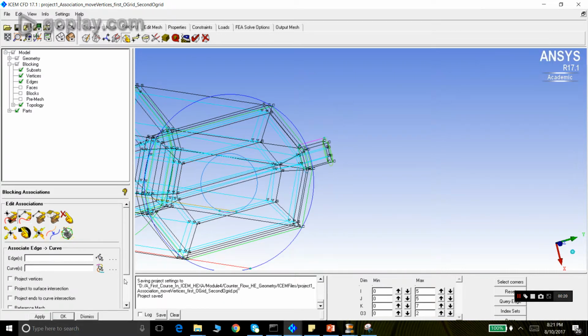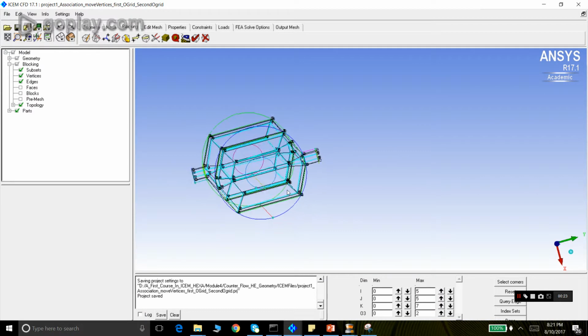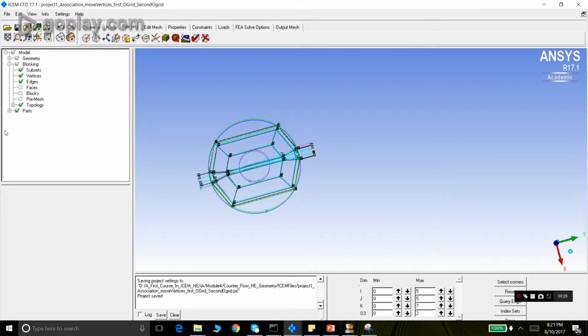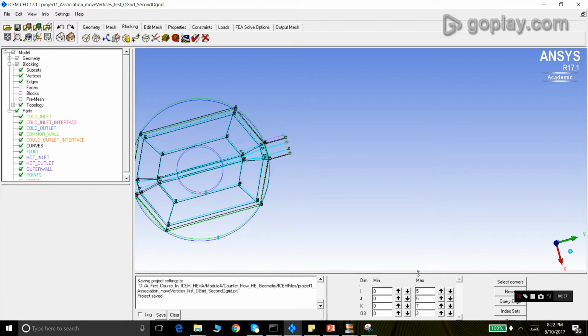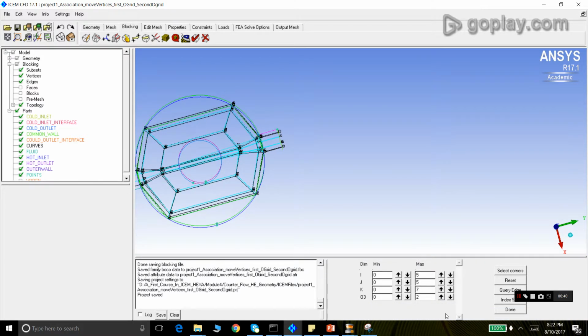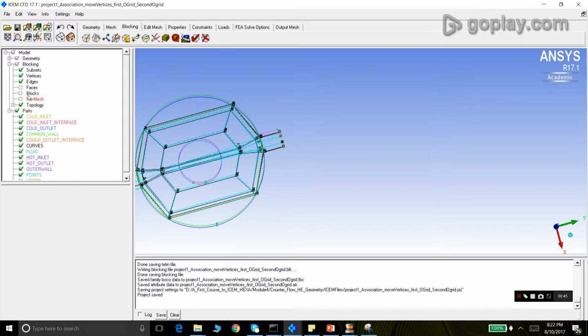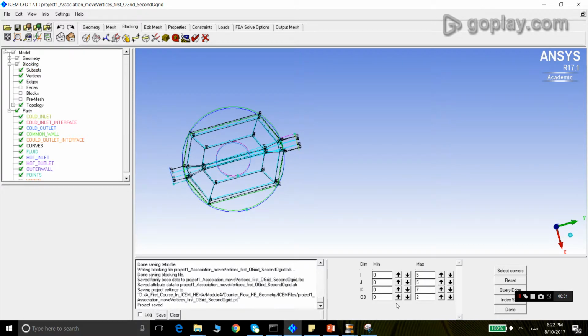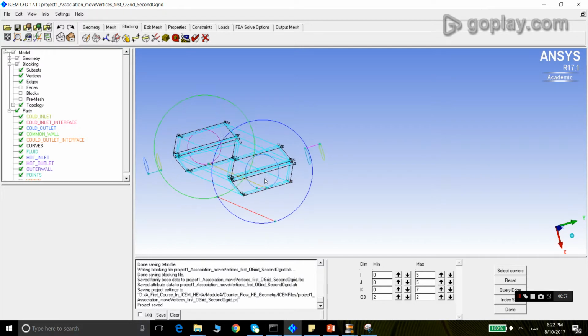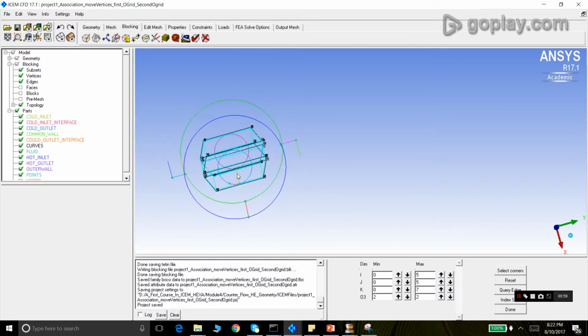Or maybe not. Before we do that, let's move the inner O grid blocks to another part, the solid part, the hot fluid part, because it's a multi-domain mesh, and so a different fluid will be flowing there. So by index control, now we will move these things to another part.